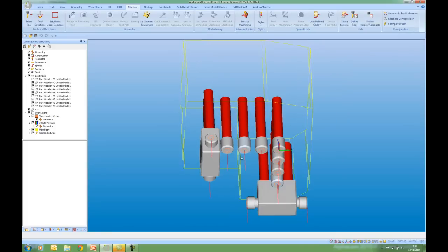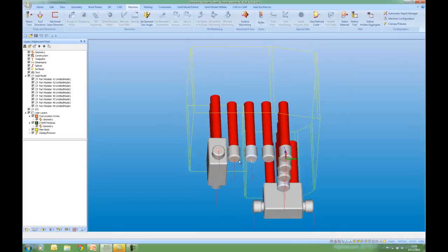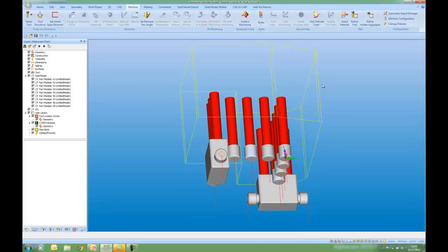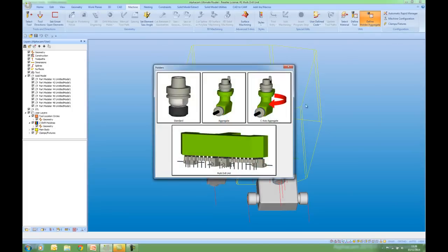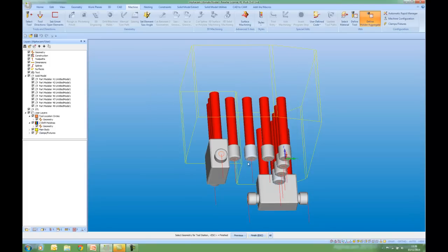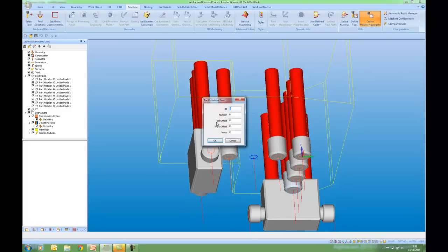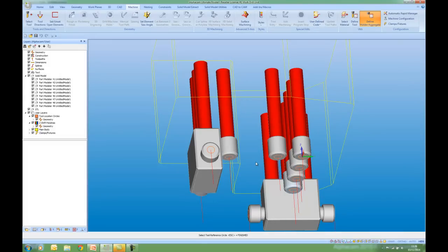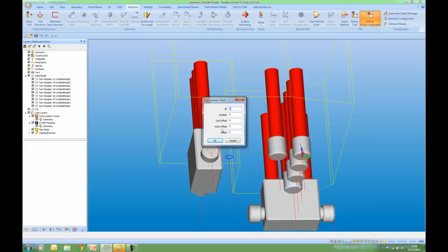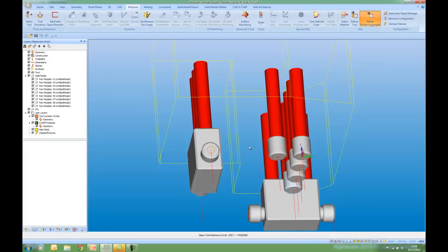So let's define just some of this for my multi-drill unit. I'm going to go to Define Holder Aggregate, and in here we have multi-drill. Pick the solid in this case, representing the tool station. Pick the circle. It has a unique ID, and the 3D polyline from the center of that circle is automatically detected. Pick my next station. Pick my reference circle. Again, a unique ID, and my polyline has been found.